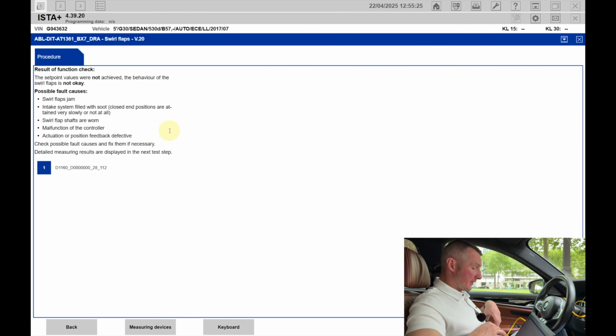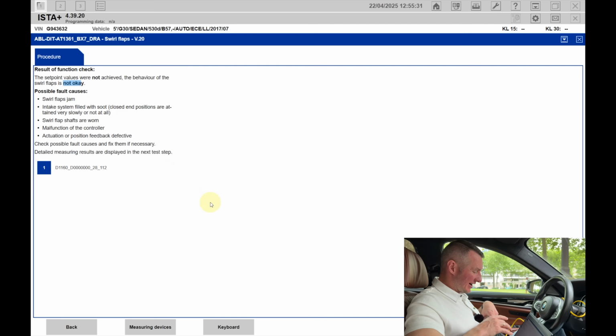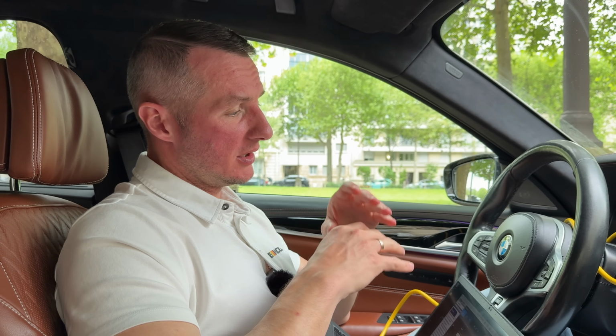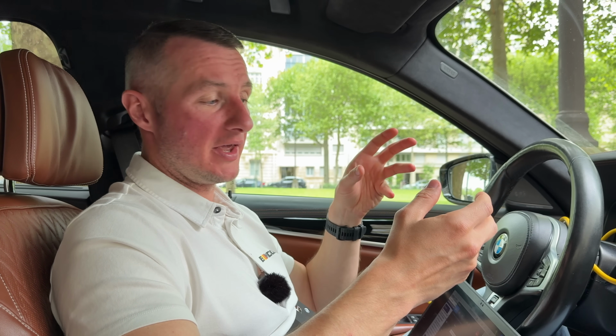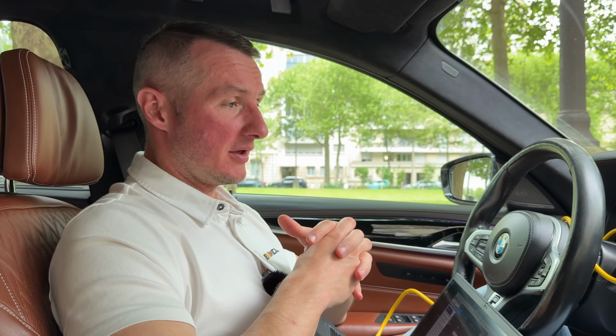One month ago, when I was performing the diagnostics for my vehicle, the test was still okay. And by the shape of those diagrams, I can see that the situation with the swirl flaps is getting worse and worse. If I was in Estonia, I would immediately stop the vehicle, open the hood, and take off the intake manifold and see the exact state of the swirl flaps. Are they falling apart or not? And of course, replacement of the intake manifold with the swirl flaps is required, because those are not separate things. For example, refurbished intake manifolds are also available on the market.